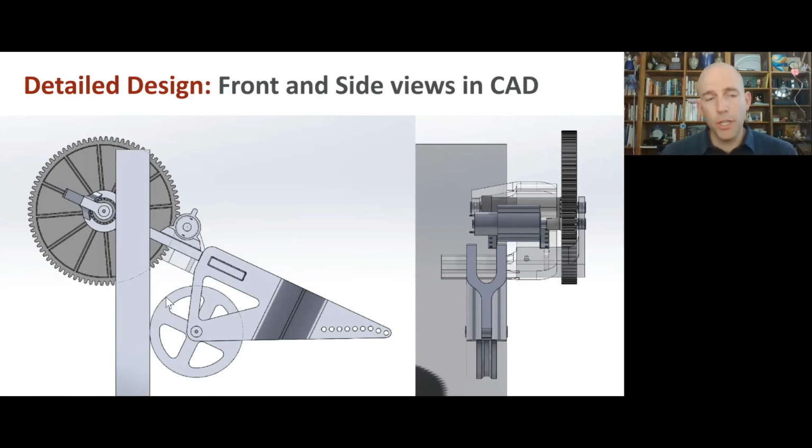This passive wheel has a pretty big radius, and that was chosen in part to manage the sizes of these two chassis elements, and in part to have low bearing friction, because you've got a big ratio of the radius of the wheel to the shaft radius, and to limit the effect of little bumps and imperfections in the surface of the door.